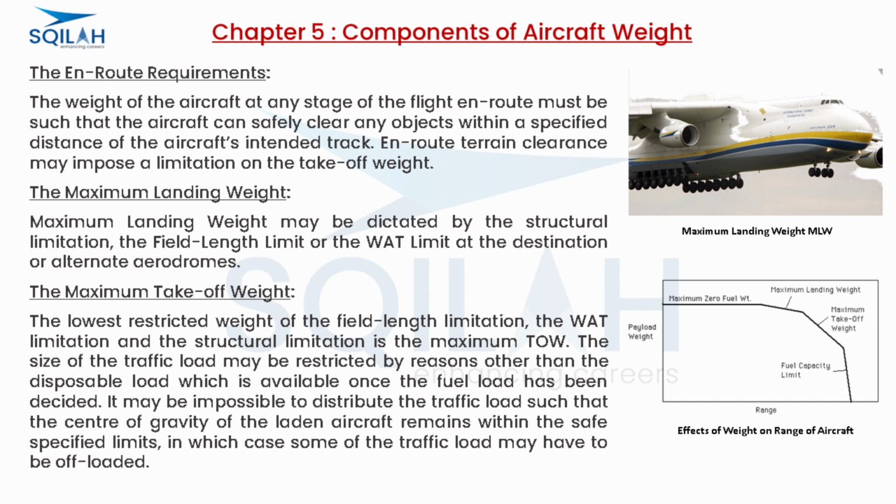The maximum landing weight. Maximum landing weight may be dictated by the structural limitation, the field length limit, or the WAT limit at the destination or alternate aerodromes. The maximum takeoff weight. The lowest restricted weight of the field length limitation, the WAT limitation, and the structural limitation is the maximum TOW. The size of the traffic load may be restricted by reasons other than the disposable load which is available once the fuel load has been decided.